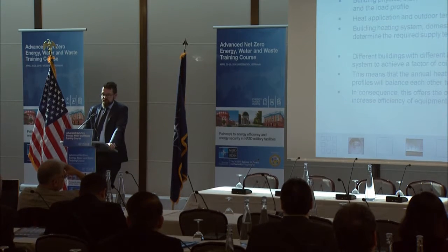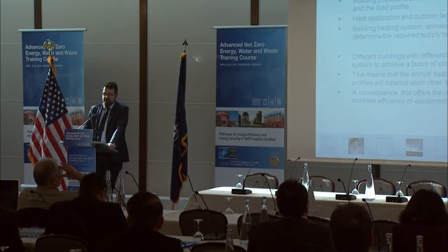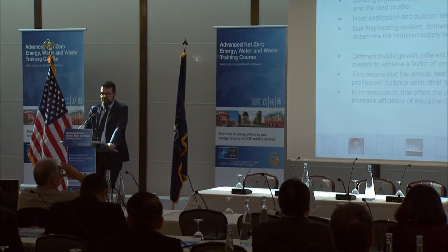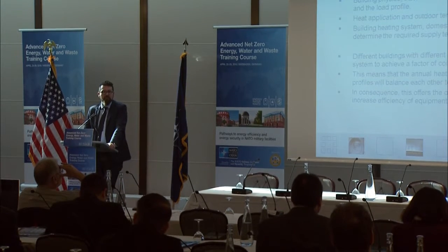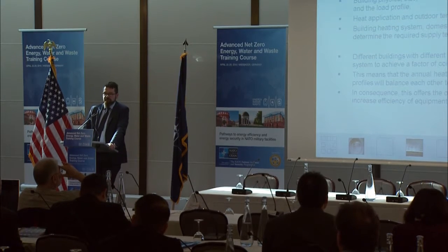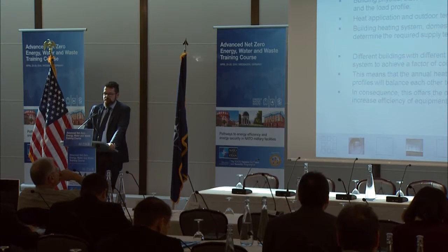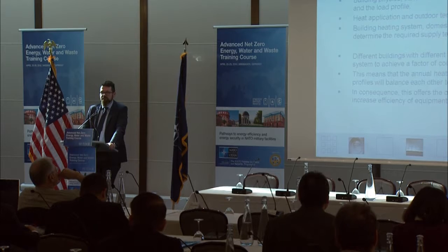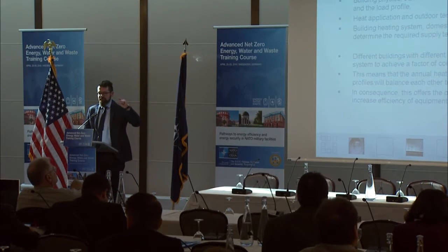Different buildings with different load profiles can be integrated into one system, and finally you come up with a factor of coincidence. This means that the annual heat demand is the same, in terms of BTUs or megawatt hours per year, but the peak load and the minimum load, in terms of BTU per hour and megawatts, is less than the sum of each single building.